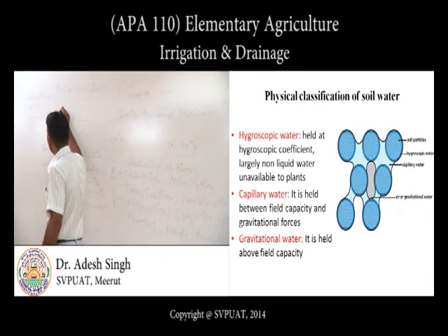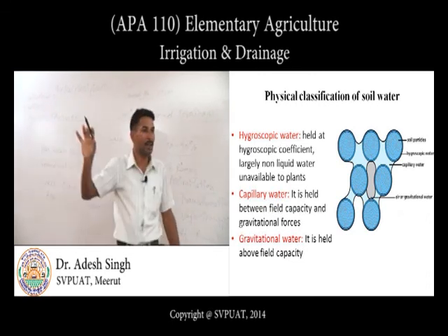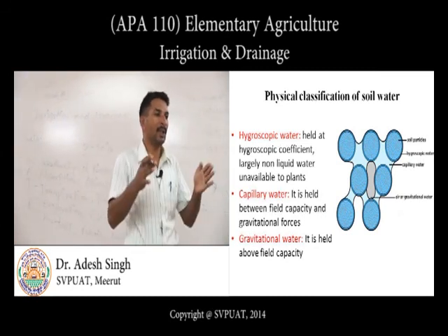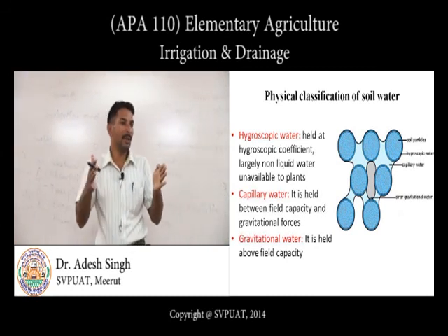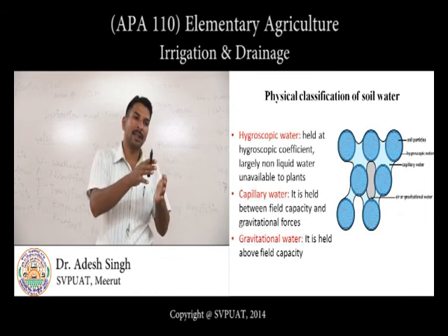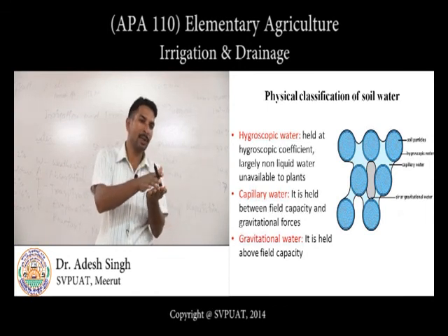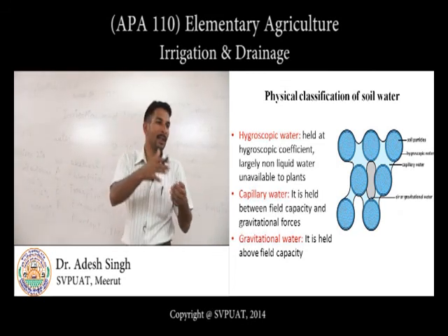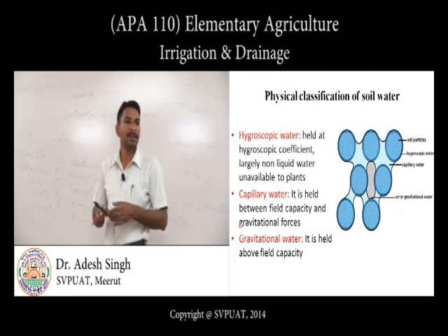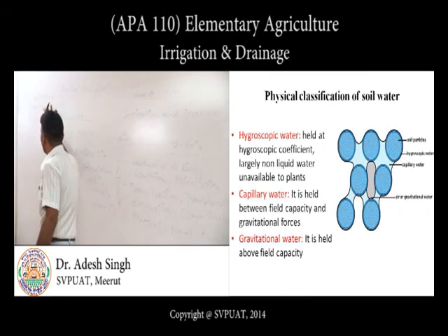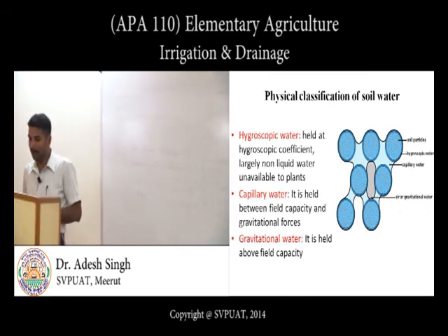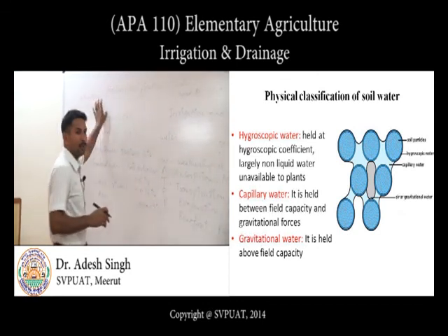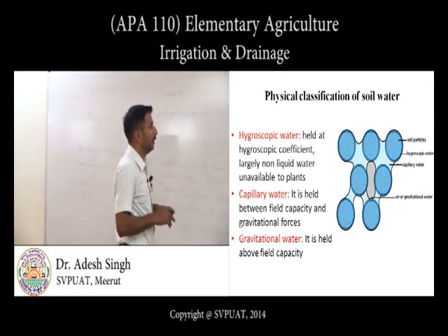And this first one is the free water, which cannot be utilized by the crop plants, and only a fraction of capillary water can be. Capillary water lies in between the saturated water in the soil pores and up to the limit of hygroscopic, where all the liquid water can split out. And when this capillary water is there, which fraction is utilized by the crop plants can be known